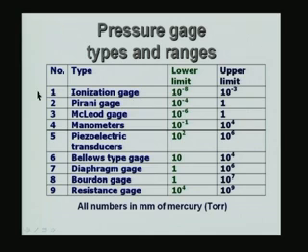For example, if you go into the space outside the atmosphere of the planets, you will reach pressures as low as what is given here. And also in many instruments which are used for chemical analysis and so on, such pressures are met with. The ionization gauge can be used from 10^-8 millimeters of mercury at the lower end to about 10^-3 millimeters of mercury at the upper end. And you will see that 10^-3 is in the vacuum, 10^-8 we will call ultra high vacuum.